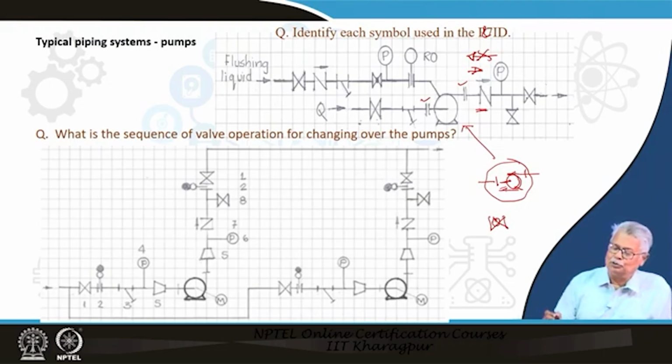Quite naturally, you would like to know what is the pressure developed by your pump. So we are expected to have a pressure gauge here. Now, you usually will also have a bleeder valve to see if your line is full or if you would like to drain something from there. Then at the discharge you have another valve which isolates this discharge side from here, and possibly you will have your globe valve somewhere here.